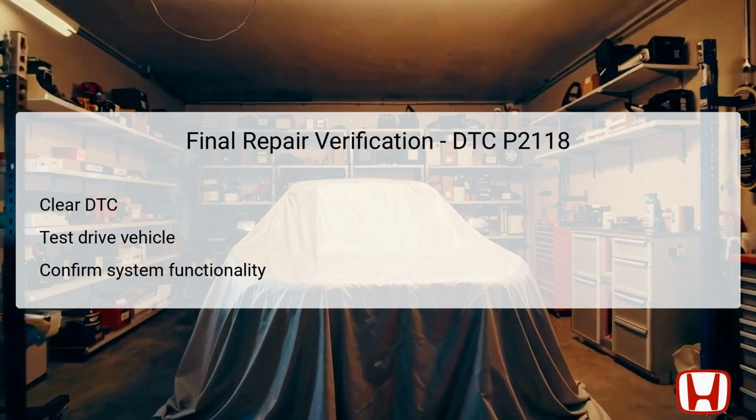During the test drive, the technician should monitor the throttle response closely to confirm that it operates smoothly and without hesitation. Observations made during the test drive are crucial for establishing that the issue has been successfully rectified. Additionally, the system's functionality should be continuously confirmed through the HDS to ensure no new DTCs arise during operation.